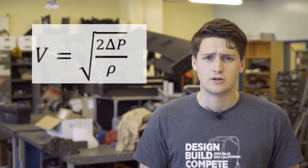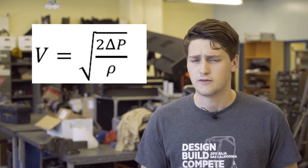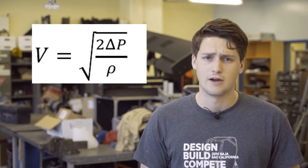So as you would have learned already from previous online lecture videos, pitot systems measure fluid velocity by comparing the stagnation pressure as measured at the entry to the Pitot tube port to a reference static pressure, which could be measured on the side of the port or from a separate location. From this, a pressure differential is taken either by means of a pressure transducer or by a water manometer or some other device, and uses this simple equation here to determine the actual velocity, wherein velocity is calculated by the square root of 2 times the difference in pressure between the two ports divided by the density.